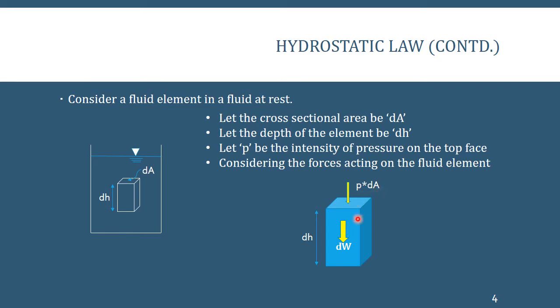Now, similarly, a pressure force will also be acting on the bottom face. The pressure force acting on the bottom face would be pressure acting on the bottom face into dA. Now, what is the pressure acting on the bottom face? I'll first show that to you. The pressure force acting on the bottom face of this element is (P plus ∂P/∂H into dH) into dA. So again, you might be feeling confused as to how this term came about.